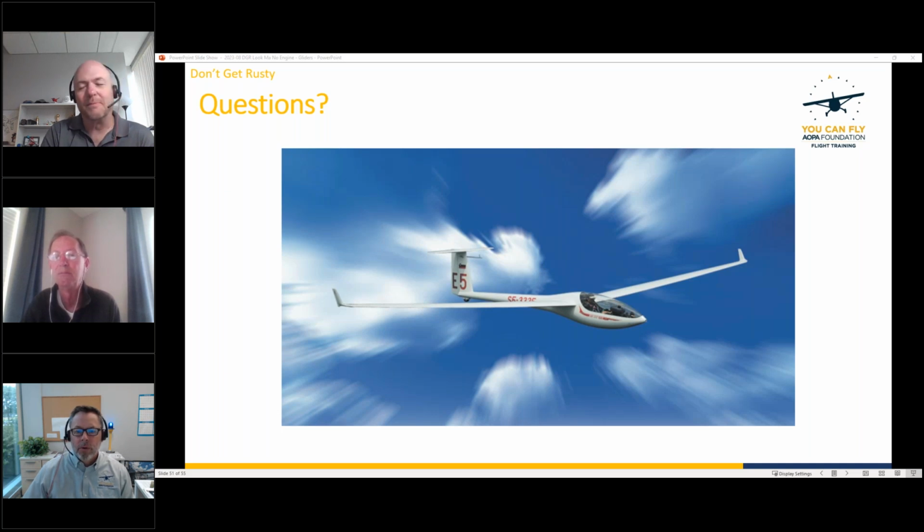Sure. So we know that, like all other aircraft, there are weight allowances. Is there a typical weight allowance for glider pilots, a rule of thumb that would get them flying in most gliders? Well, most of the gliders these days are European design, and they have certification limits of, I believe, no more than 240 pounds in any one seat. So there's kind of your limit.